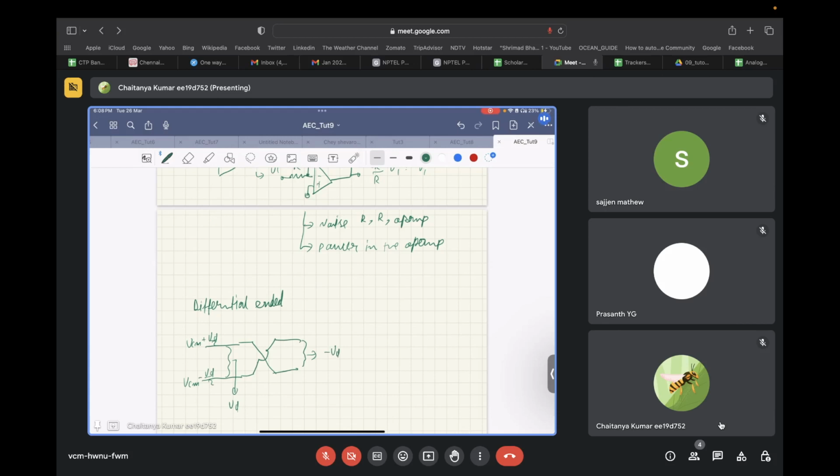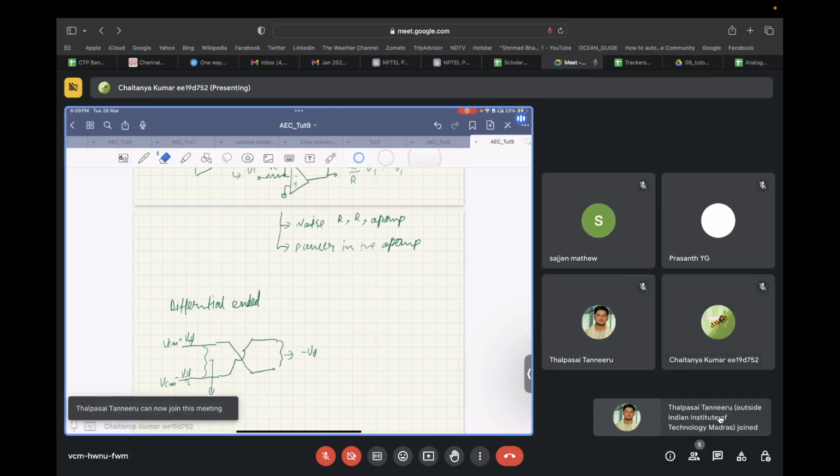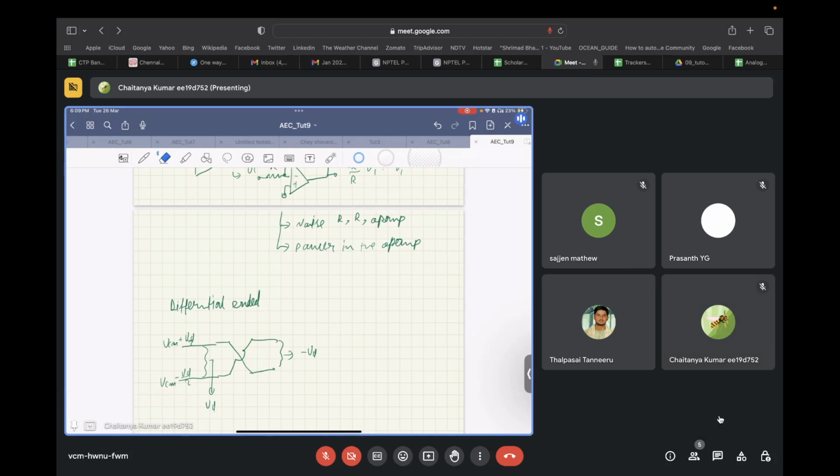So there is no power that needs to be burned, or no noise that gets injected due to an actual circuit that performs inversion. Inversion you basically get for free. So this is one of the key important features of fully differential circuits.